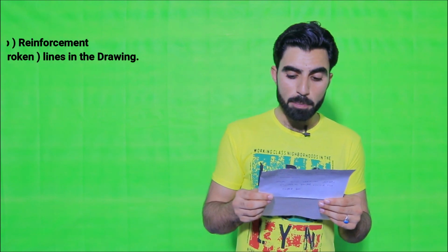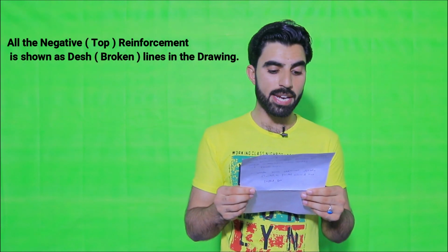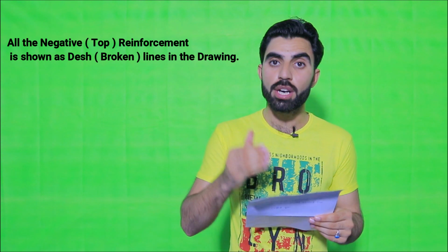The second one is about distribution bars. It is also called negative top reinforcement. As you know, distribution bars are placed in an RCC slab at the top. So the top reinforcement bars are shown as dash or broken lines in the drawing. The distribution bars should be shown as broken or dash lines. Okay, so this is very useful. These are two points. The third one is lap length for M20 grade concrete.